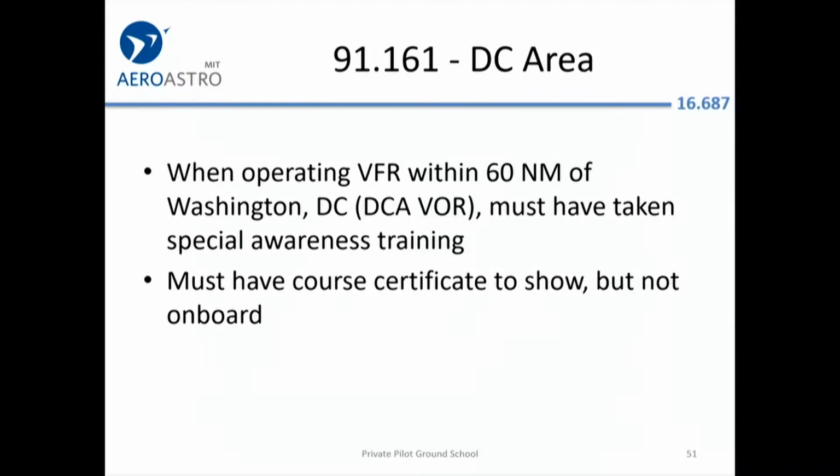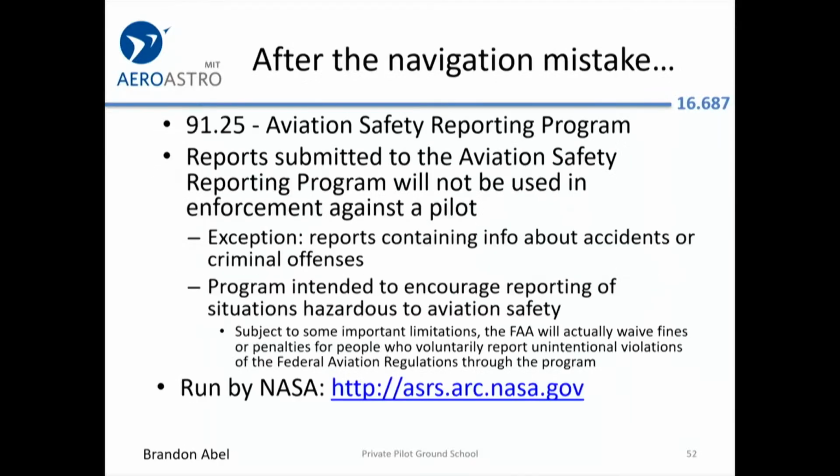They're not that hard to go down to Gaithersburg. VFR, you have to go in from certain gates. You have to file a flight plan in advance, and you have to keep a unique transponder code so that air traffic control can track you. So if you have any brilliant ideas for how folks in DC could do things better, you can just get in a little Piper or Cessna or Cirrus at Hanscom, zip down to Gaithersburg, and there you are.